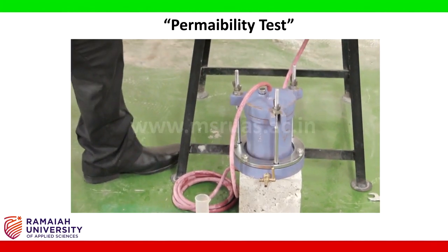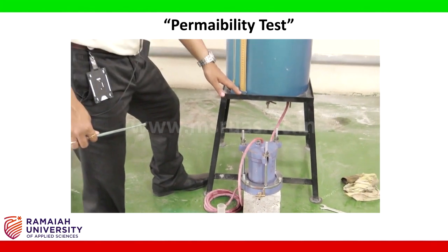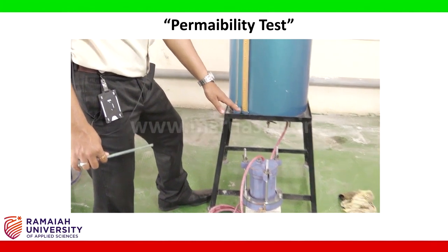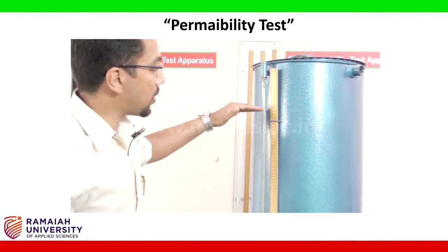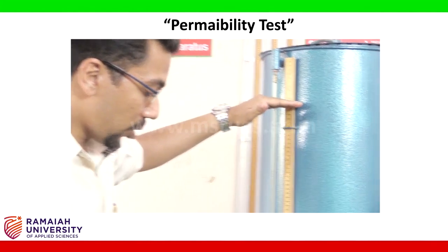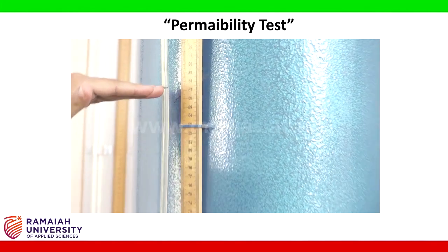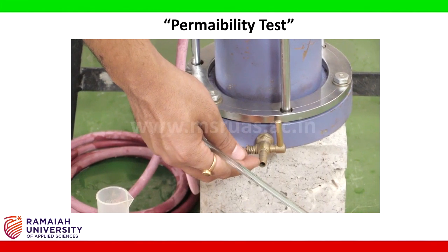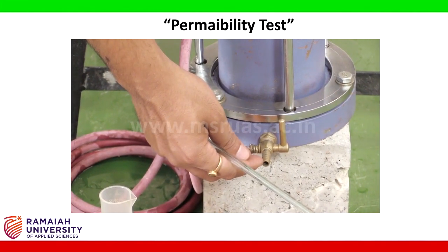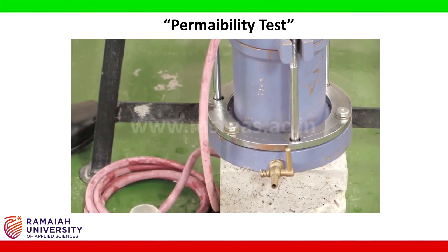So to begin with, before you start taking the readings, it is required for you to measure the head of the water with respect to the reservoir which holds the water. So measure the head till the center of this exit pipe and start the experimental process.